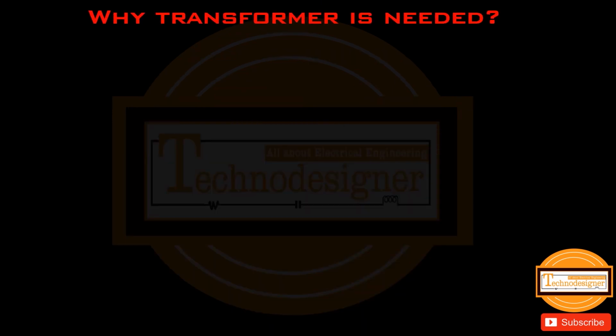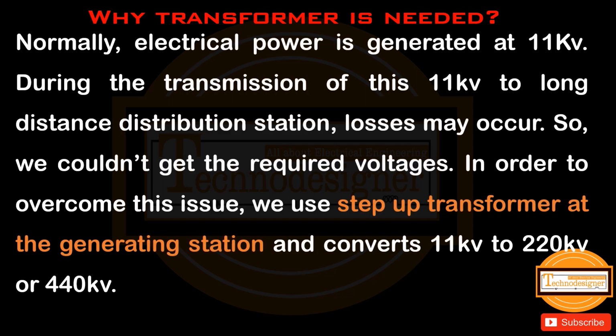Why transformer is needed? Normally, electrical power is generated at 11 kV. During the transmission of this 11 kV to long-distance distribution station, losses may occur. So, we couldn't get the required voltages. In order to overcome this issue, we use step-up transformer at the generating station and convert 11 kV to 220 kV or 440 kV.